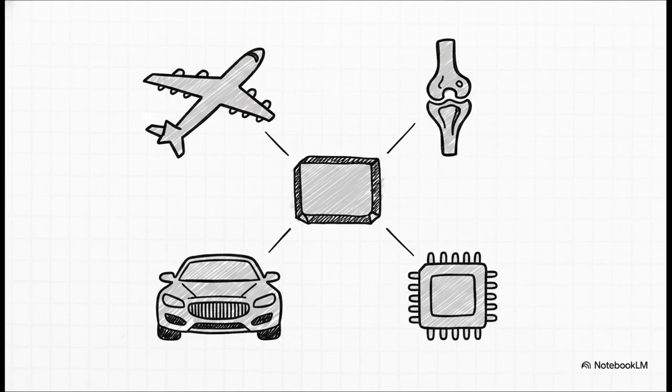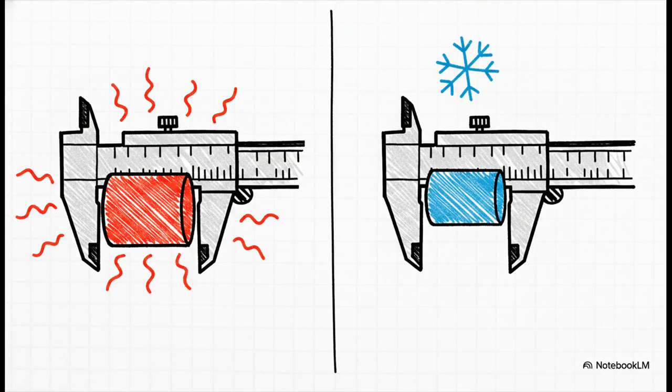Automotive focuses on 12L14 and 1045 steel for high-volume surface-hardened drivetrains, while the electronics sector needs the high conductivity and super-precise tolerances of C360 brass and tellurium copper. But here's the catch. Even when you match the perfect material to the industry, the physics of machining can still completely trick you. Take thermal expansion in plastics, for example.